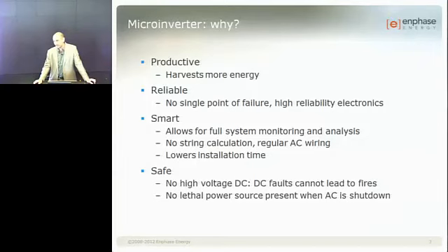All the wiring is in AC versus a whole bunch of DC wiring. And I don't know if you've ever done this, but if you put even 3 modules in series and you make a short and you try to open the connector, you basically get a fire. Because any bad contact in the DC current loop will create an arc which will reach 4,000 Kelvin pretty easily. So in this case, we only have one module connected in DC to an inverter running at 20, 30 volts. You simply cannot get an arc with that system.